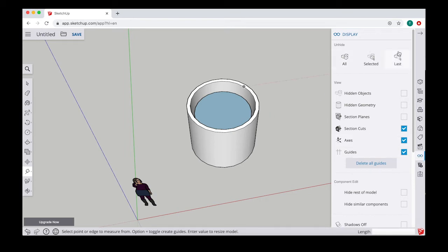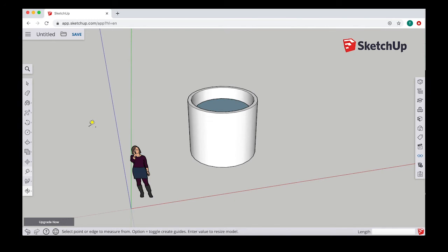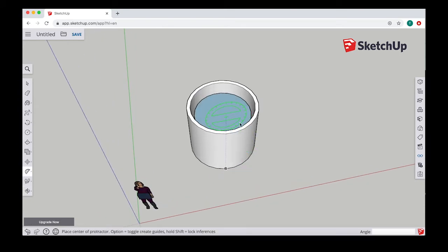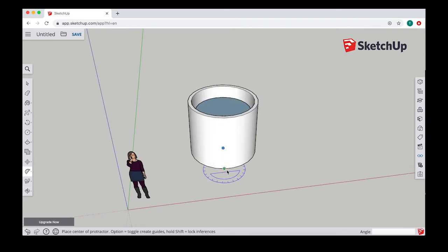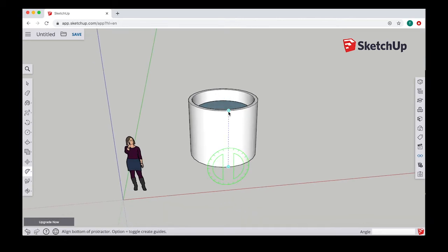Next, in a similar way, you have your protractor tool, which operates in a similar way of taking measurements, but essentially it will take measurements of the angle. You can alternate between the planes using the arrow keys, as previously mentioned. Then if you snap it to a shape, and maybe check that this is a 90-degree angle here, you can click once and then drag, and then click again, and it will give you that angle in the bottom right corner.